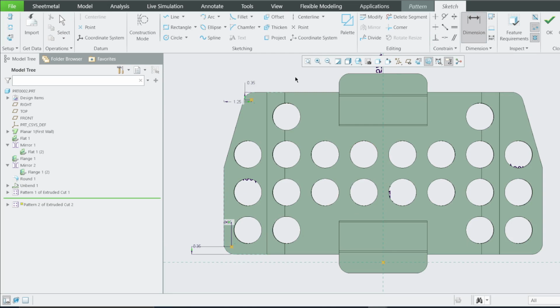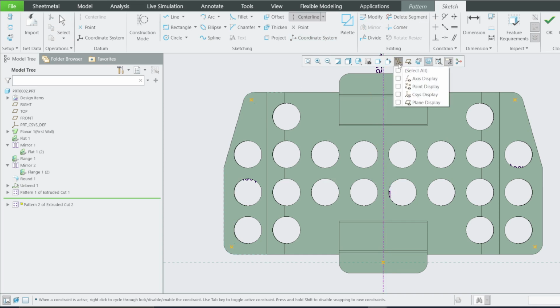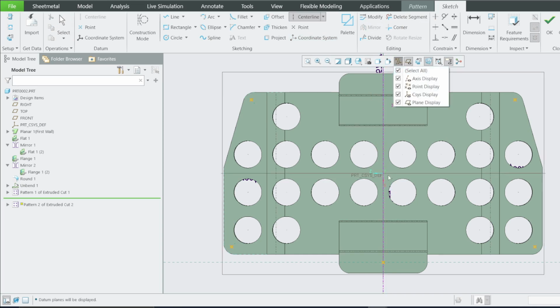And we can now have our center line, and we can now select this point, press Ctrl this point, mirror on this line to get them the other side. Again, another center line here. Let me activate this one here, because I want a center line here like that. Then deactivate them.